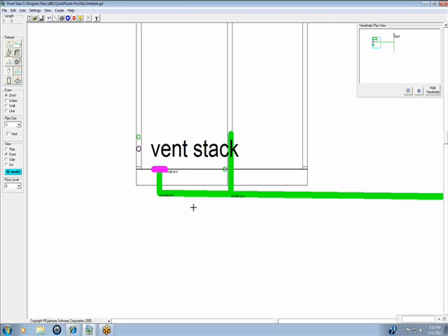And so that would be legal in your case? That would also work with me, except that my maximum distance is 4.5 feet, trap and vent. It's amazing how the code is so different. Ours is 10 feet between a water closet or a 3-inch trap and a vent.